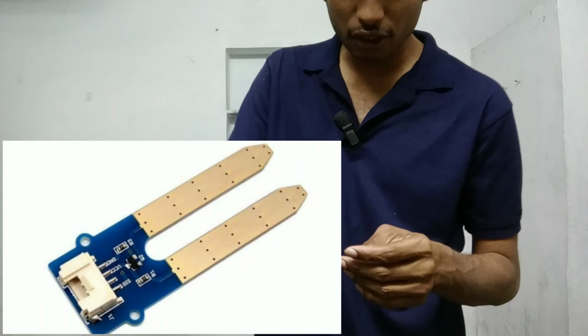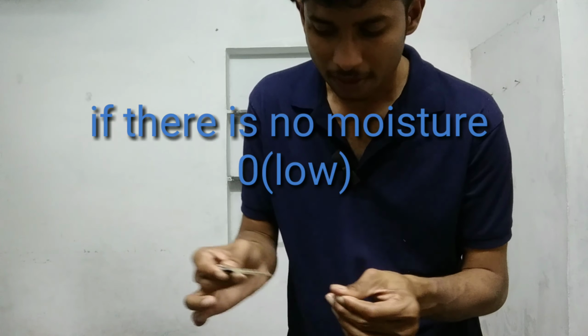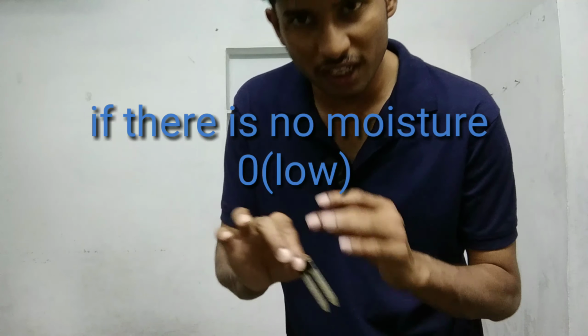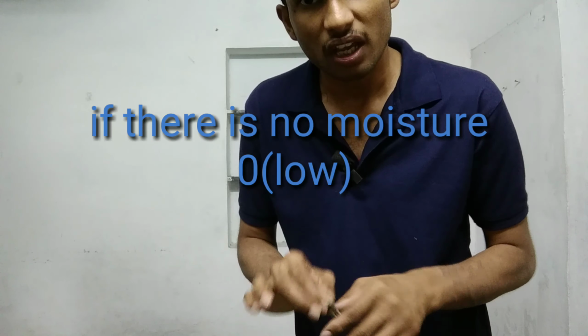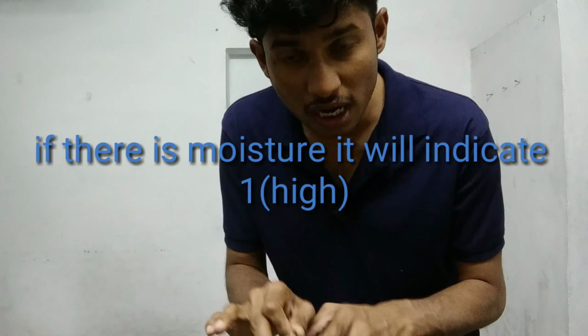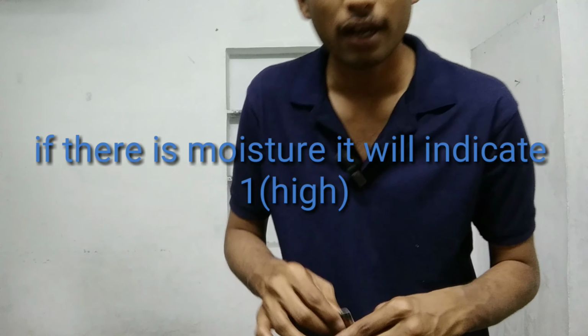This is dug into the soil wherever we want to check the moisture level. This is the digital pin. If there is no moisture, then it will indicate 0. If there is moisture content in that soil, then it will write 1 to the Arduino board.